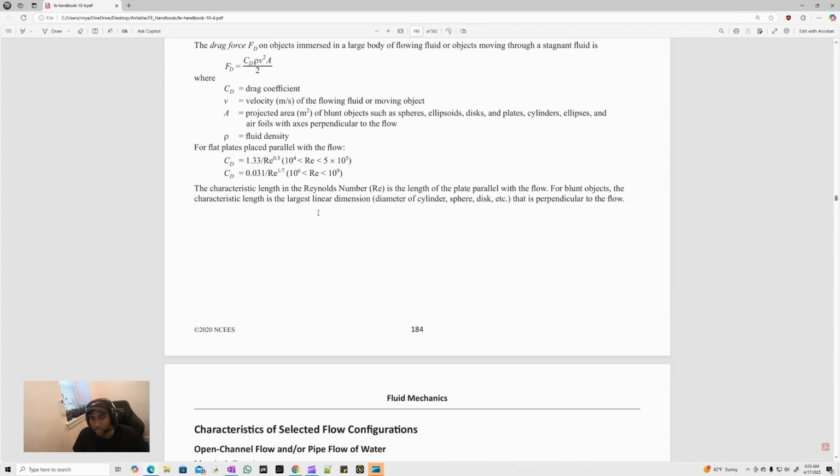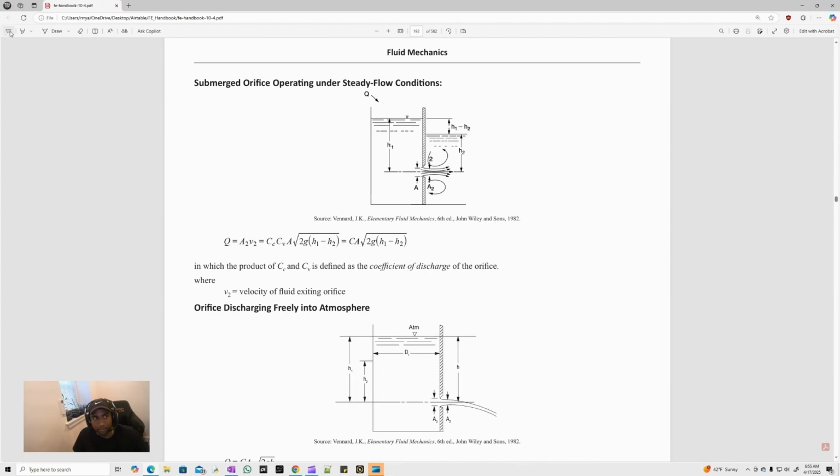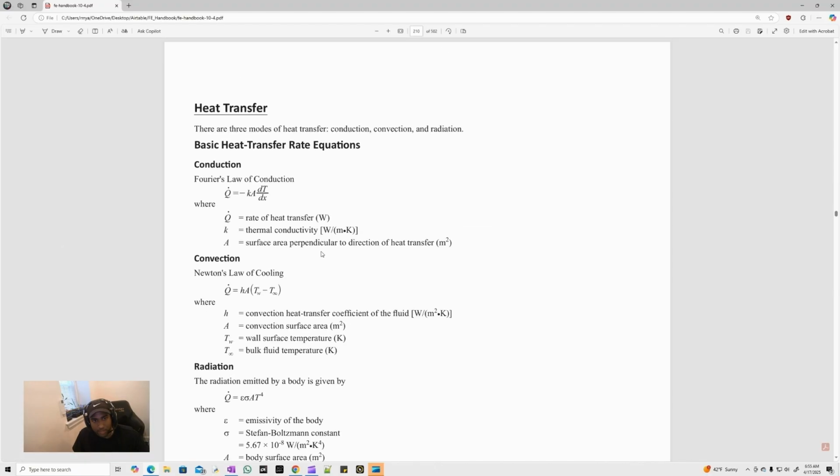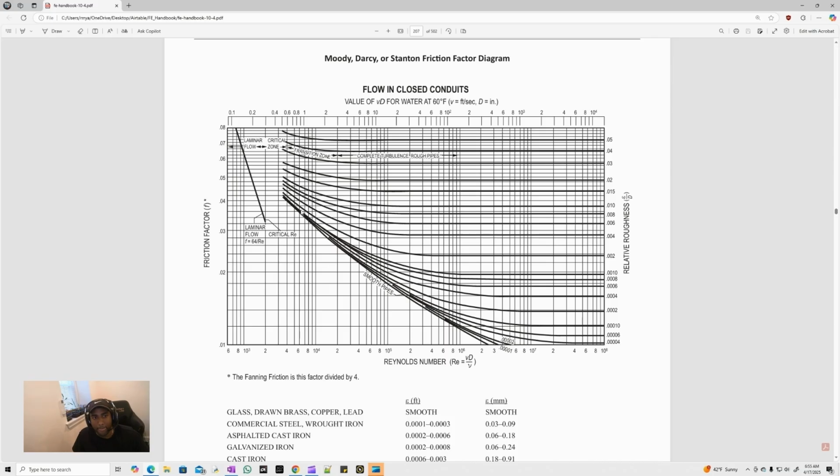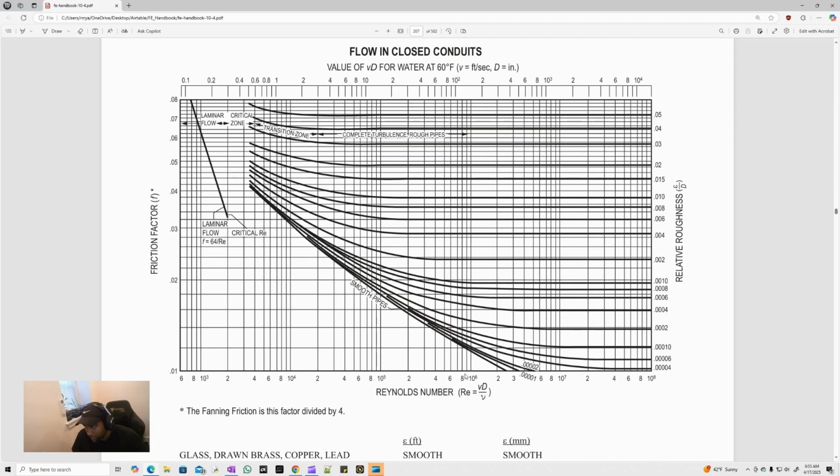So we're going to end up using that Moody diagram, and it's at the end of the fluid mechanics section, which is this. You can see on the x-axis we have the Reynolds number. We have a relative roughness value. That's a dimensionless term. It's that roughness that we're given divided by the diameter. We go up, knowing the Reynolds number, to a certain relative roughness value and move over to the left to get that friction factor value. So that's our general plan for this